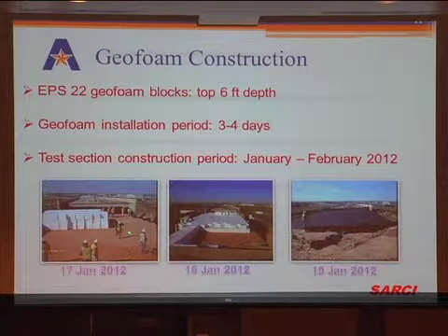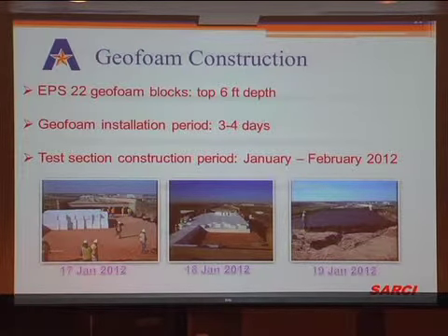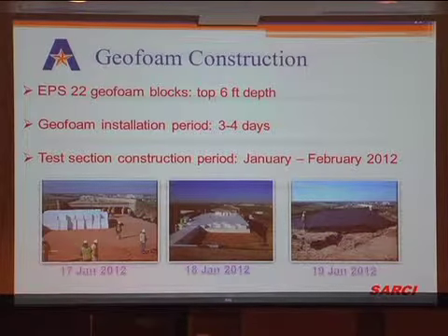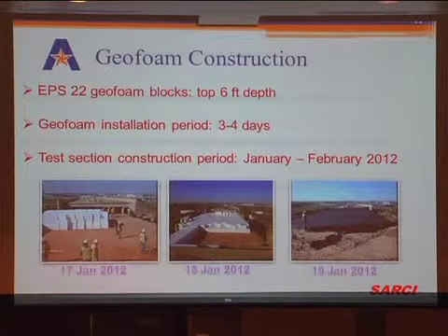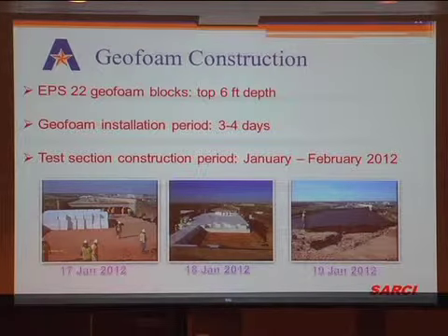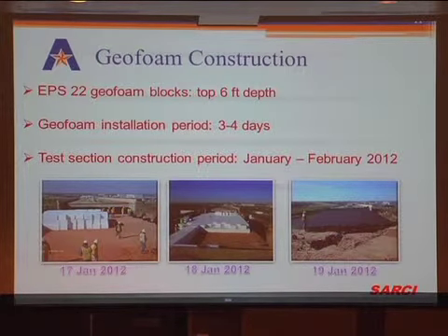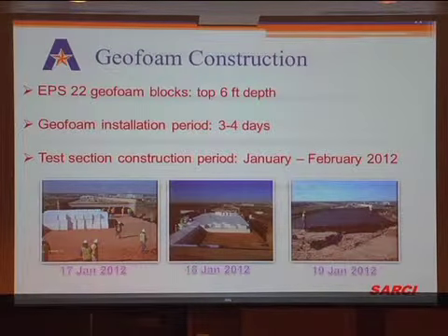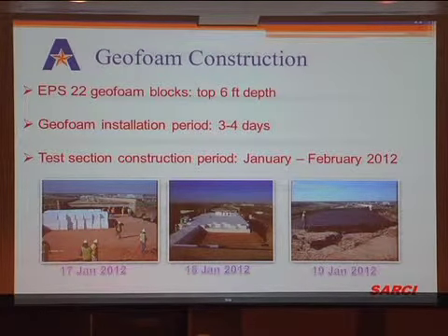So that when you place this foam, you really had to place a nice granular layer as the bedding layer. And that's what you're seeing here, the sand layer. Underneath the sand, you have a geomembrane used for covering, because you want the foam to be protected from infiltrating oil leaks coming from your trucks or something, that can soften the material.